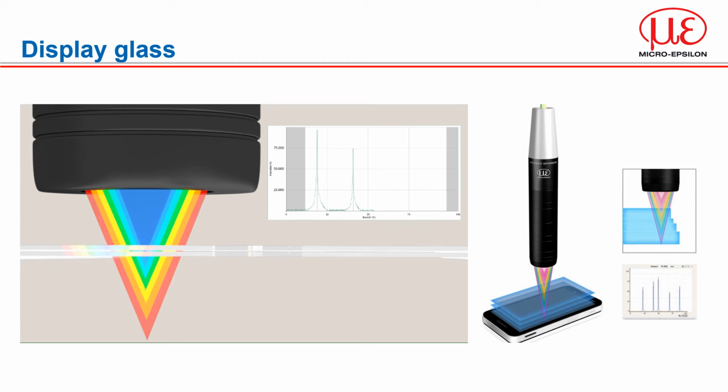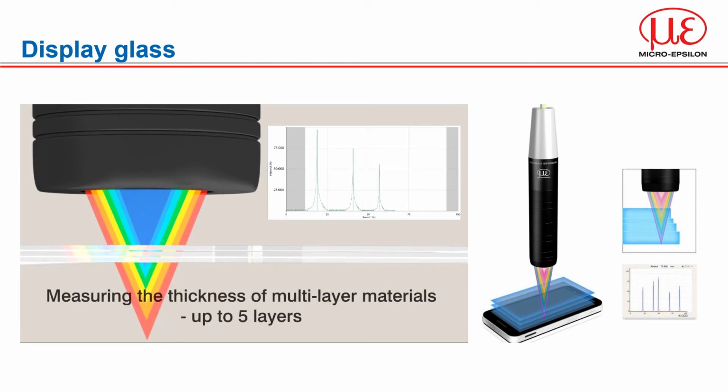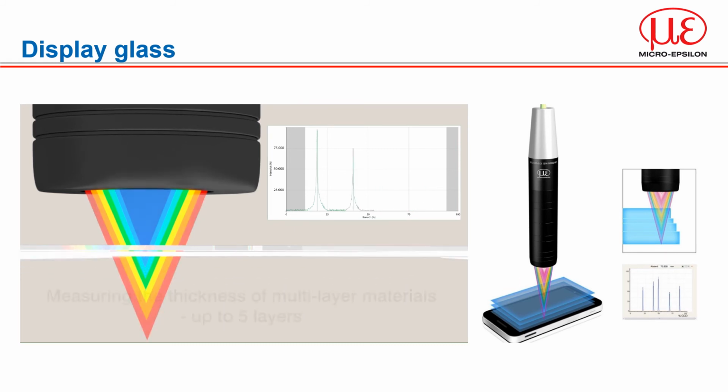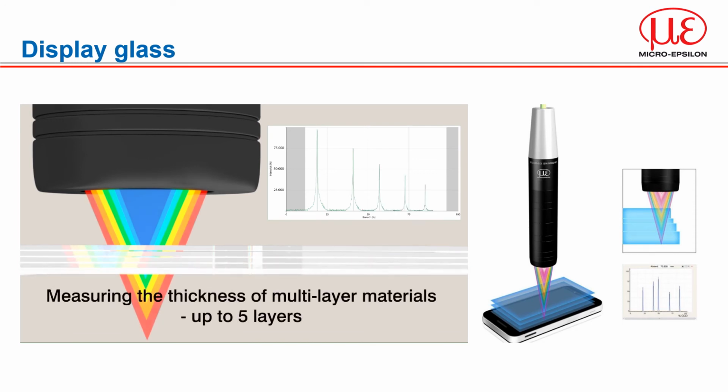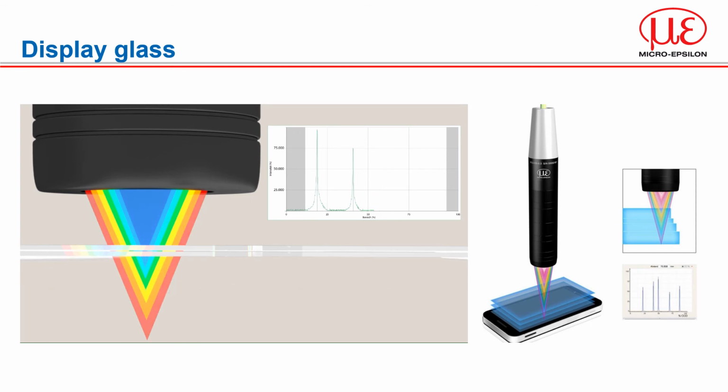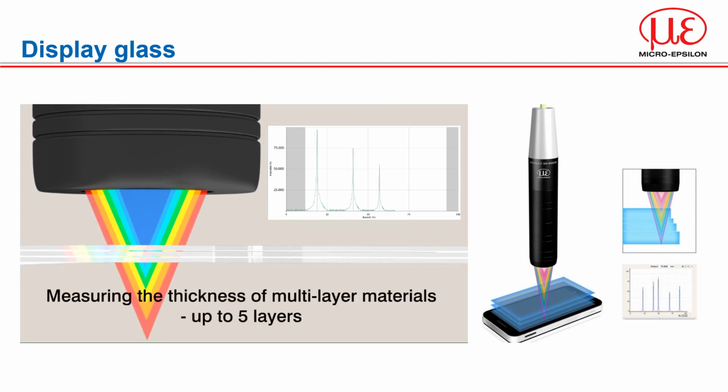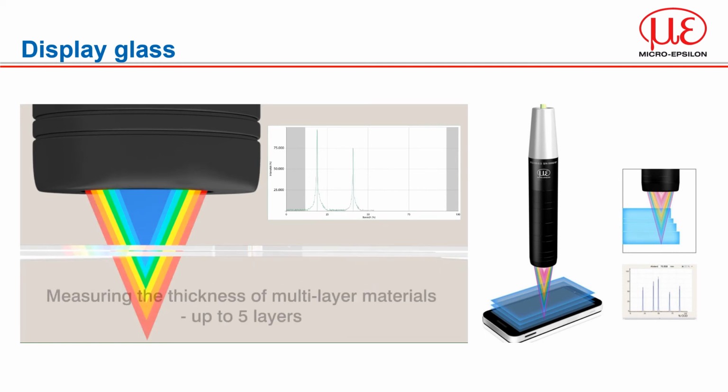When manufacturing multi-layer, laminated and curved glass for airplanes, automotive and architectural applications, precise thickness measurement of each layer is important. Confocal sensors master these tasks. If the curvature of the adjacent layers does not comply with the required measurement, there is a risk of increased stress which might lead to delamination of the glass.